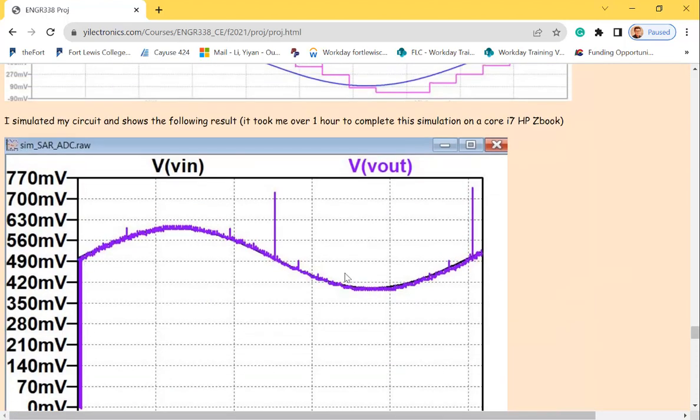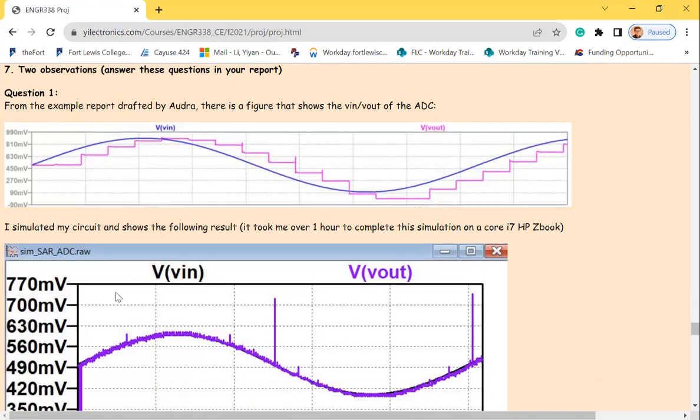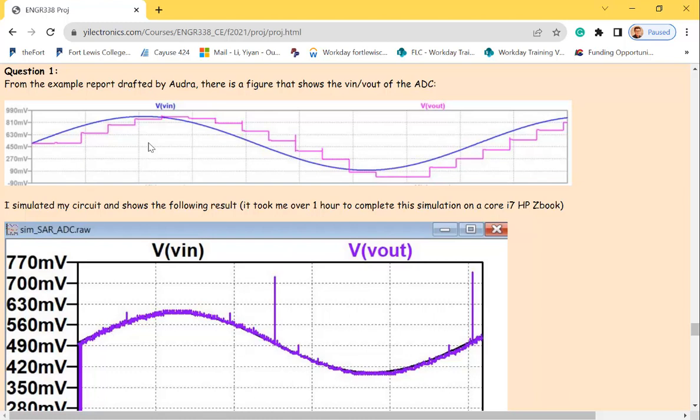It's super noisy, but it's an 8-bit ADC result. It's a sine wave. It's trying to follow that. If you have a low frequency for the clock, then you can finish the simulation in a few seconds, but the result is not as good as the one like this. So this one, compared to this one, is the same circuit, but I just used a pretty fast clock instead of, you can see the clock, it's about 10 times slower than each step over here.